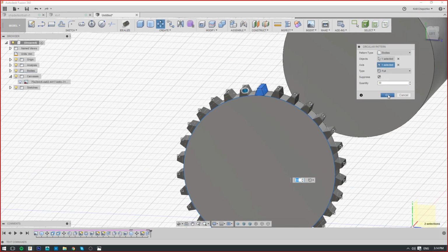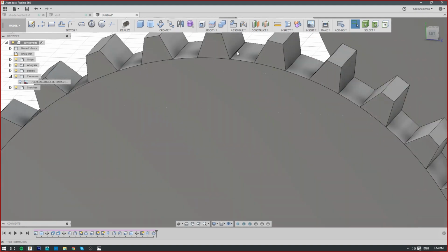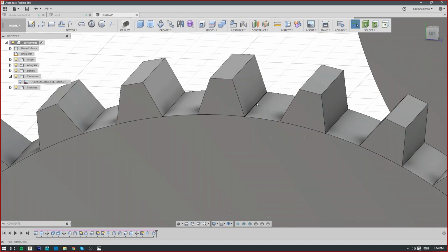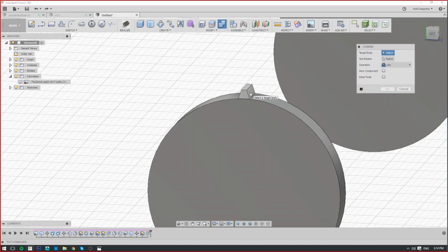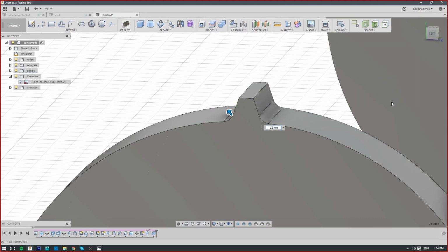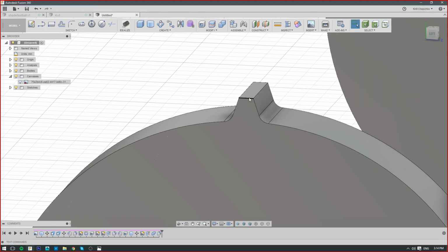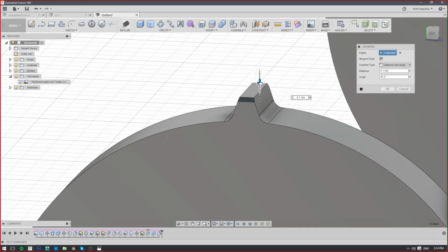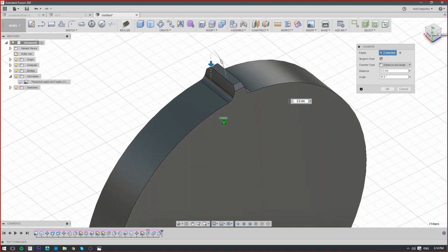But the point is, if you do this, you end up with like 30 bodies, and then you have to go and merge them, and then go one by one and fillet the connecting point. So I've recently been doing it the other way. I will join it. I will do the edge treatment right away, like this. I will also do maybe a chamfer here. Just some extras that will show up only in the render, if at all, if it's something close up.